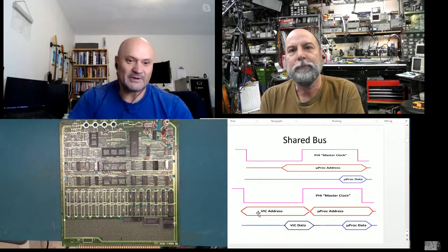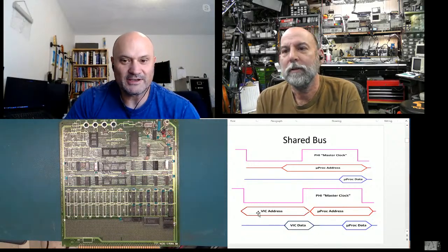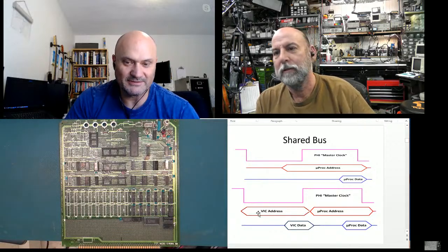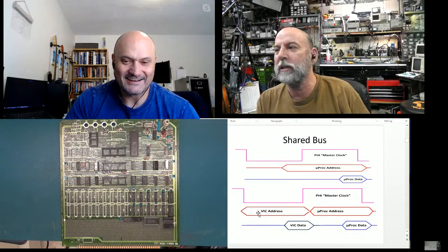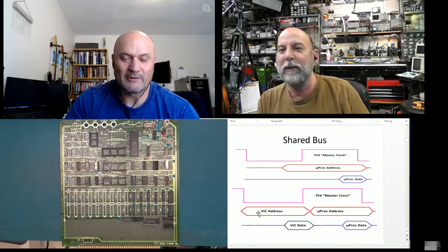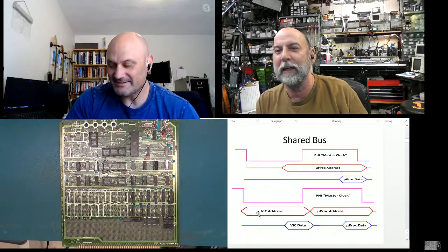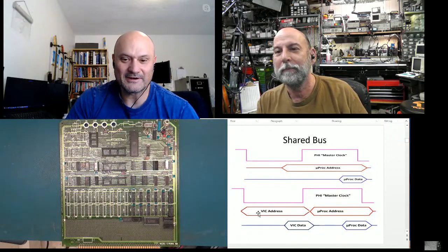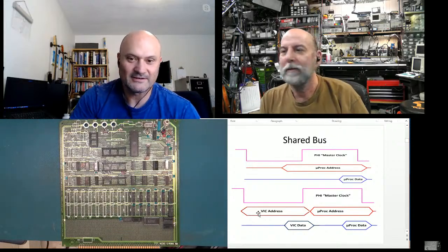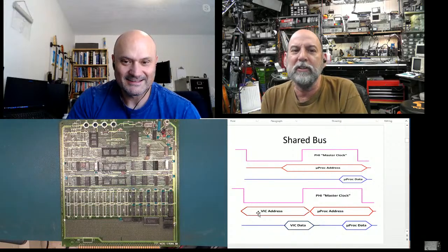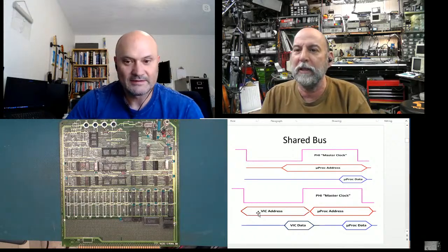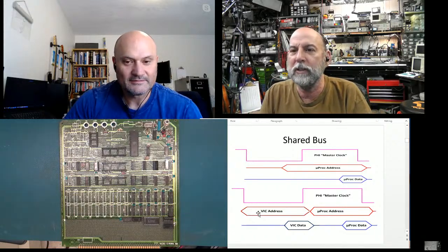So what would happen if I had a C64 motherboard and I couldn't find a 6510 to put in it? You can take a 6502 in a CPLD or an FPGA, or just a PGA, and emulate it. So I'd have to have that bus available signal? Yes. The whole thing won't work. You have to have that zero-page port, or the whole thing won't work, because that's how it controls some of the things about the C64.